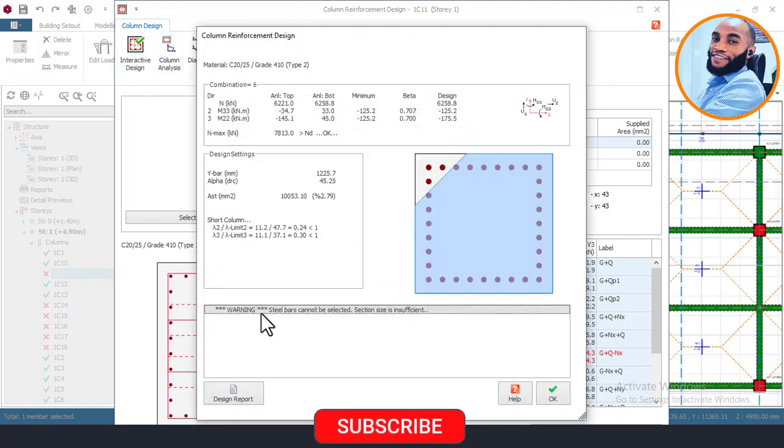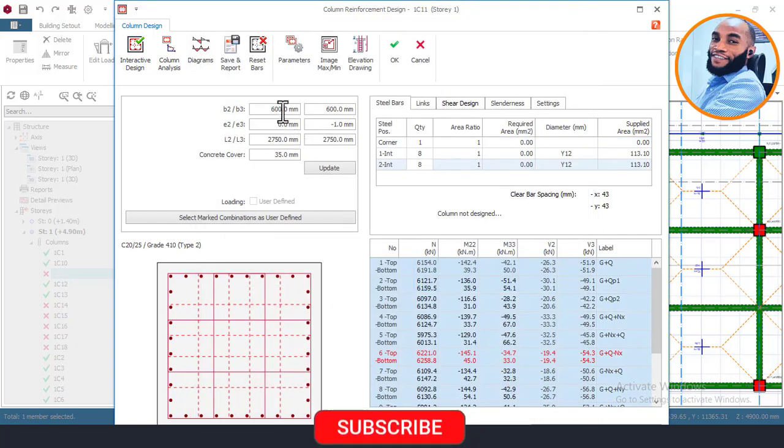Okay, now on this one it says the warning that steel bars cannot be selected. Section size is insufficient. That means that the size of this column here is not sufficient. So I'll have to come here again. Let me add it up to 650 and see if that will be okay. 650 by 650. You can choose to use a rectangular column if you want. Okay, and I'll make that 0, and I'll come here and then update.